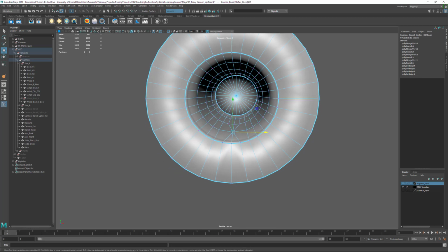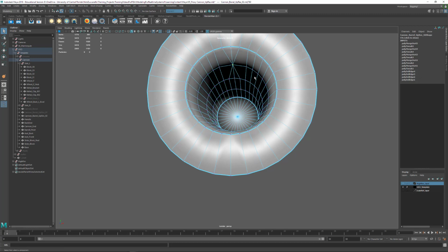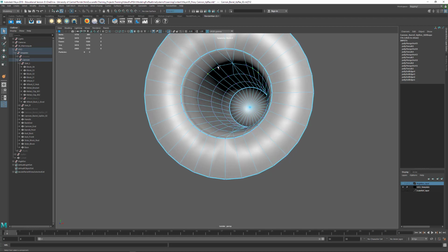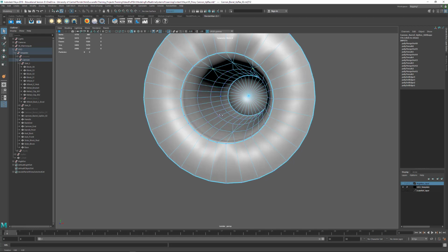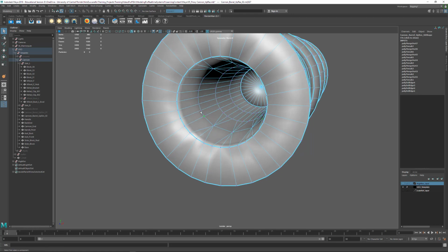So let's say we do those 3. Then I'll tap Q to make it easier to select this. And Shift right click, merge vertices to center, just like that. And let's do these 3 together. I'll tap G for my last command, like that. These 3 together, tap G for that.